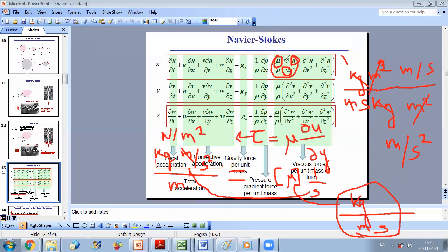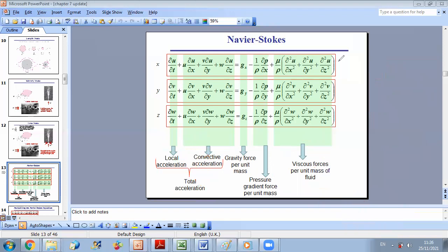If you replace g by 9.81 in the equation, this will not make it any more general, because if you apply it in English system, it will not work. To apply it in English system, you should replace g by 32.2. Okay, so an equation to be general, we should be able to apply it in any type of units, in any type of systems. Okay, and this requires that all terms of our equation will have the same unit, the same dimension. Okay, which is here the dimension of an acceleration.